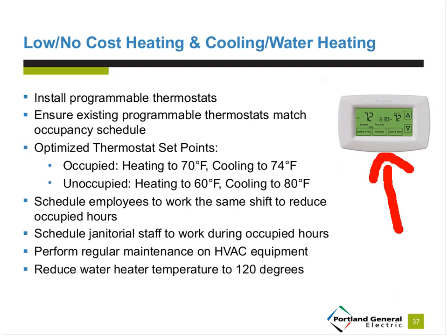Programmable thermostats, yay. Like I said before, if you have an old thermostat, the one that you have to twist, it has a dial on it, that is old, and it can become uncalibrated over time. So you feel comfortable in that turn dial that says 60, 65 degrees. That feels great to you, but actually your furnace is running at 70 degrees. You just don't know it. So you think 65 is actually 70, and that's a way that you're using energy.